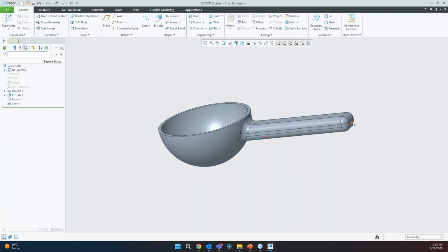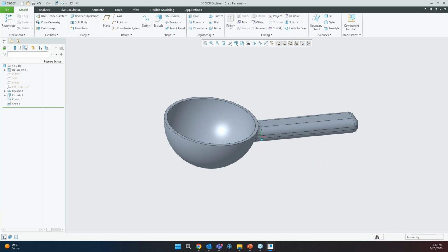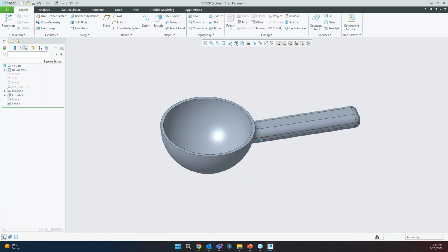So again, I select the surface here and then the scoop surface by pressing and holding shift, and it just selects the entire seeded boundary, so that my selection process remains faster, and I have more time to do other things than individually selecting each option here.